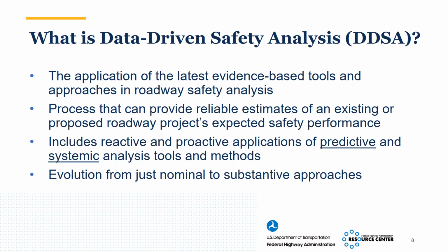It's pretty safe to say within the profession, we're seeing an evolution from nominal safety, just saying whether or not a standard is met or some condition exists, yay or nay, a very binary type approach. Did we meet the warrant? Yes or no? Did we exceed or fall beneath the average crash rate? These yes or no type questions, that's nominal safety. We're really seeing an evolution to substantive approaches, where we derive performance measures for safety, similar to the way that we have been deriving them for operations.